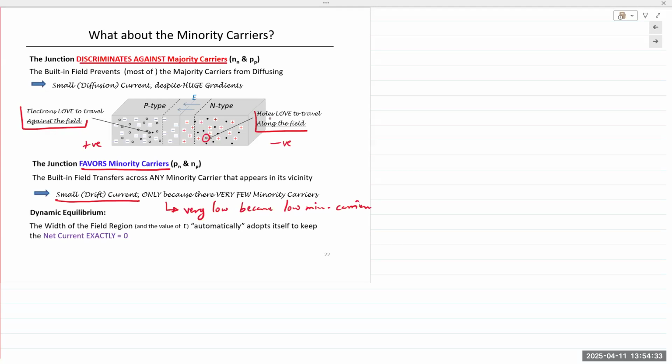Again, you're working against the barrier. If you apply just 0.1 volt, 0.2 volt, 0.3 volt, the electrons do not acquire sufficient energy to cross over. But for silicon, as you start crossing 0.5, 0.6, 0.7, they acquire sufficient energy, so they are overcoming the junction barrier and crossing over the junction.